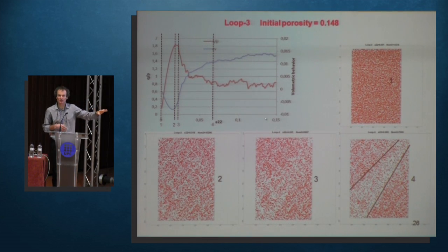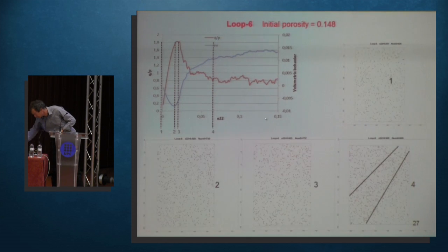So inside the shear band, you are very dilating, you destroy the dense structures, and on the contrary, you are promoting structures with a large number of grains, that is to say, structures prone to dilate. We have exactly the same result, not with 3 grains, but with 6 grains. And you can observe that you have a localization of the loop 6 within the shear band, where the concentration of this kind of loop is much higher.